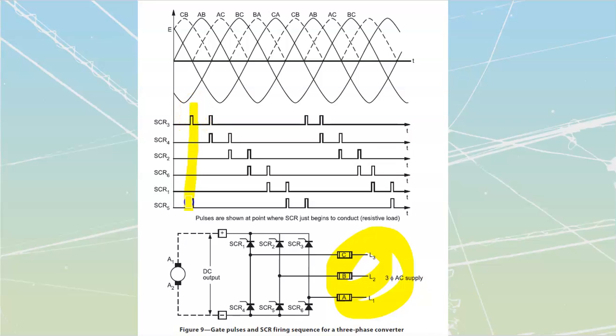Taking a look, we're not going to go through every blip on here, but if I follow these down, this is a timing diagram across the bottom over here. I know, we love them. That timing diagram shows that only 2 SCRs are fired at this point. The other ones, if they're not fired, are going to be blocking. So I'm just going to put check marks next to the 2 that are shown as being fired. That's going to be my SCR3 over here and my SCR5 over here. And then I'm going to examine those as far as the lines themselves go.